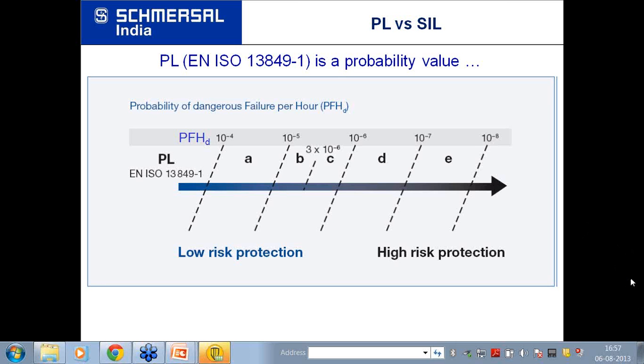Mr. G. Siva Prasad has asked another question. Is there any alternative device available in case of PLC with cost effectiveness? Sir, I don't know what kind of application you have and where you want to have this alternative device, but you can achieve the same thing with a lot of relays. It will give you cost effectiveness, but it will decrease your productivity. It will decrease the reliability.